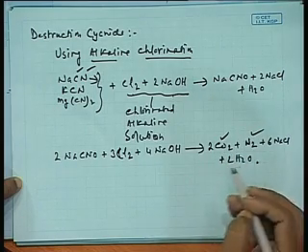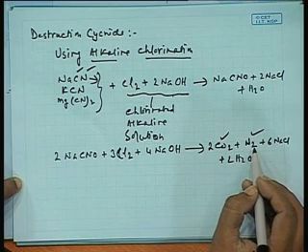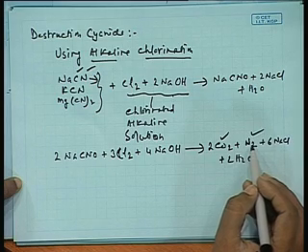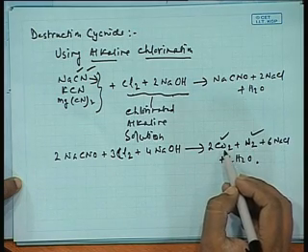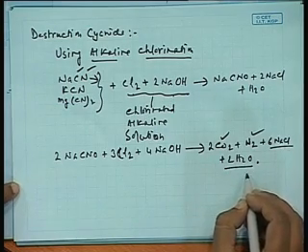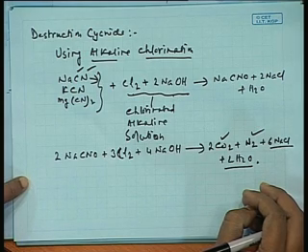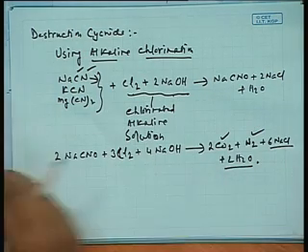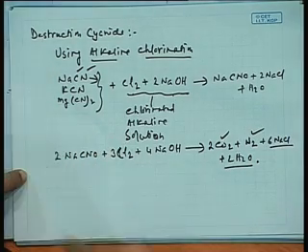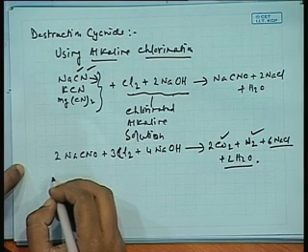If you stir the water for quite a while, nitrogen does not remain, as it is not very soluble in water, so it leaves the water, as would carbon dioxide at STP. And what we find is sodium chloride and 2H2O. So the water is almost completely purified from cyanides. This is a typical tertiary treatment that generally finds good use.